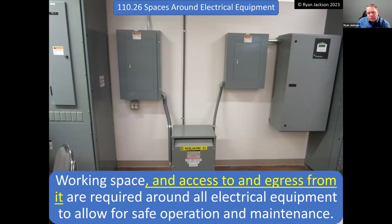But here's the bottom line. This rule stands on its own. It says all equipment must ultimately be capable of being operated and maintained safely. So how much space you need in front of a given piece of equipment might vary based on what that equipment is. And we don't really do a great job of telling you in the NEC that you need 3 feet in front of a panelboard, and you need this in front of a transformer, and you need this in front of a disconnect,